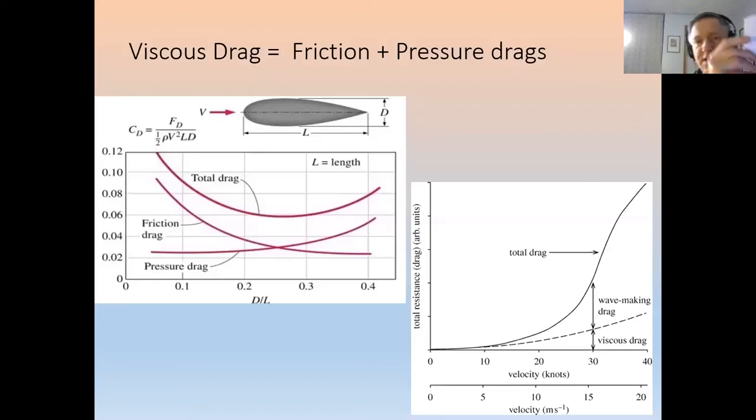Okay, so you're a designer, and this is a shape. Here's a shape of something, a little submarine, let's say. Well, the friction drag is the drag across the top of this. So it's the resistance of the, say, water flowing against the top of this. So it's a function of the velocity and the roughness of this device. But the pressure drag on this is high. So if water comes in here, it hits this, bang, high impact, high pressure, and then I get these eddies over here. So I have a low pressure here and a high pressure here. So I have this vacuum cleaner trying to pull it this way, and this impacting water hitting it this way.